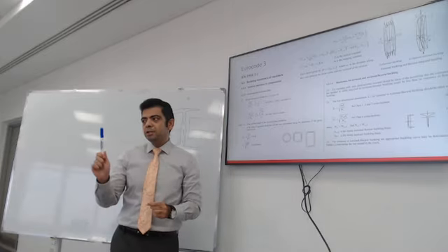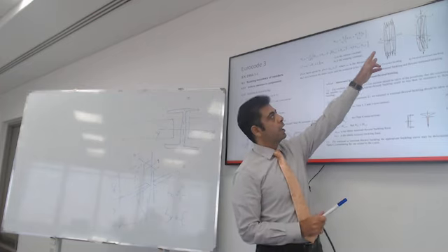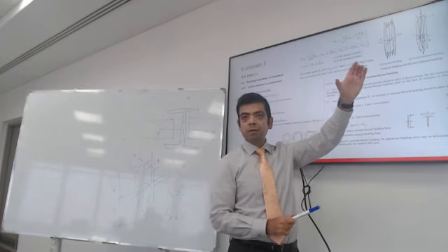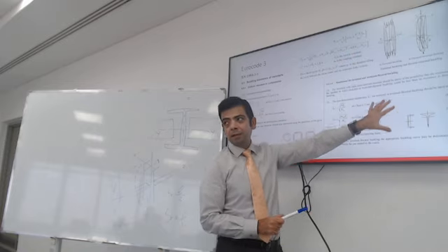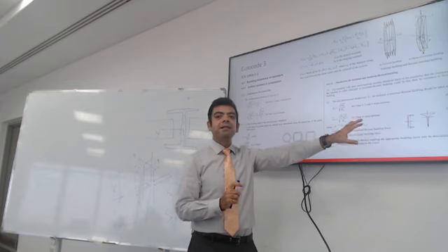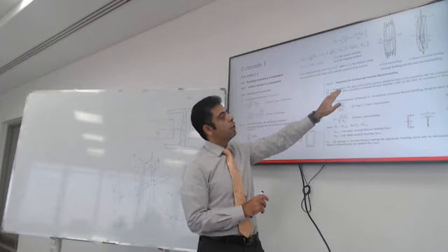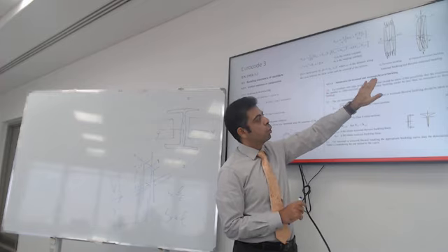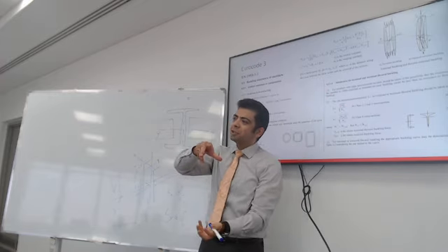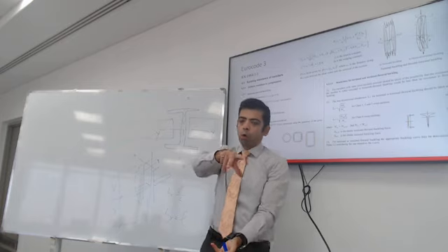Here is another interesting check. If you don't use a section that looks like a cross like this, or an open channel, you don't have to get here. But let's say you're designing an element that needs to have a certain shape like this. That will introduce something called torsional or torsional-flexural buckling. It introduces additional buckling shapes. It could buckle in flexure and warp.